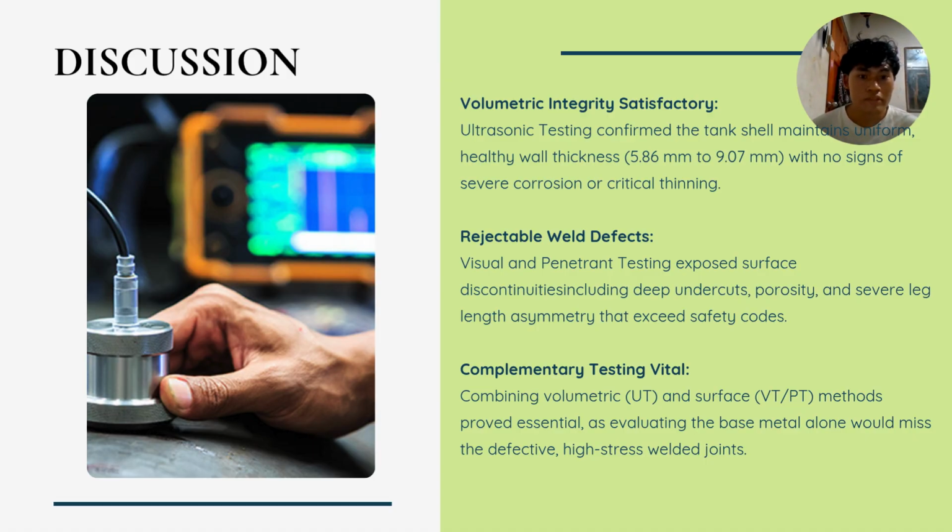Second, we found rejectable weld defects. Even though the shell is strong, our visual and penetrant testing exposed serious surface flaws on the joint, including deep undercut, surface porosity, and bad leg length that fail standard safety codes.